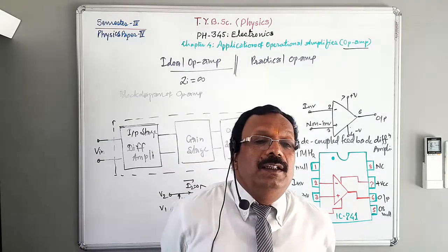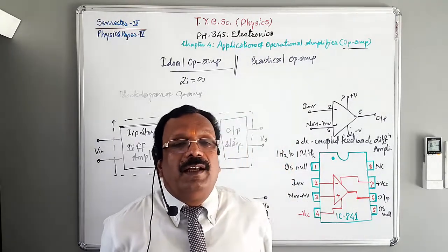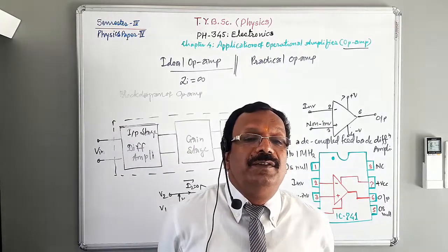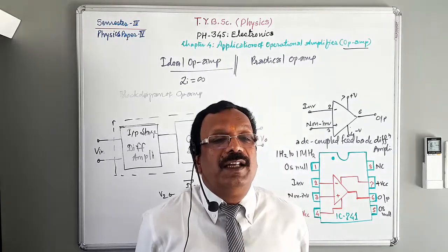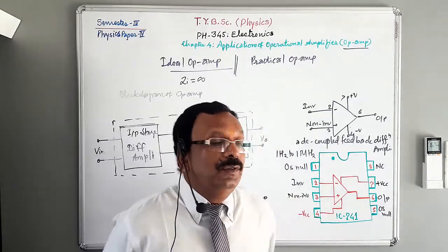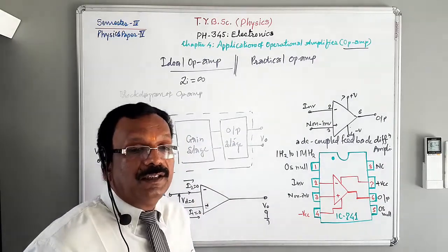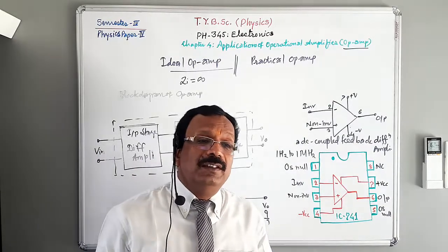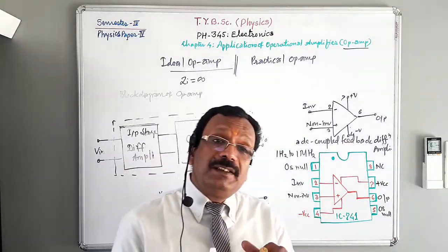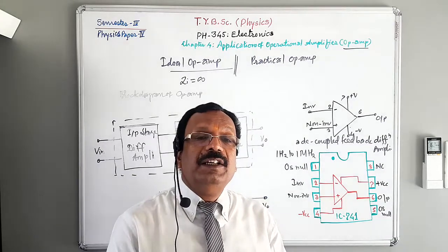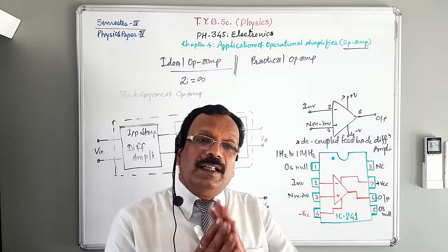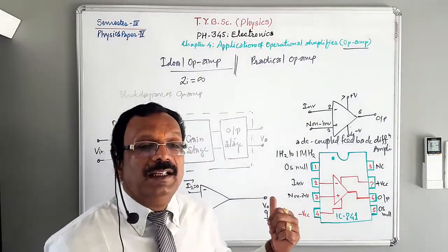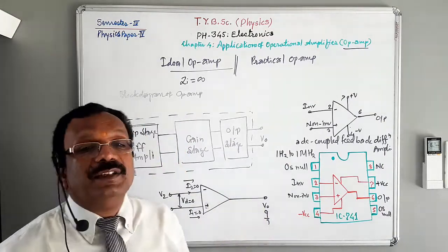When the input impedance of an ideal op-amp is infinite, that means no current flows into the amplifier input terminals, and the figure shows I1 is equal to I2 is equal to 0. When input impedance is high, it is not necessary to do external work in order to supply the input. Any source can drive it and there is no loading on the driver stage.